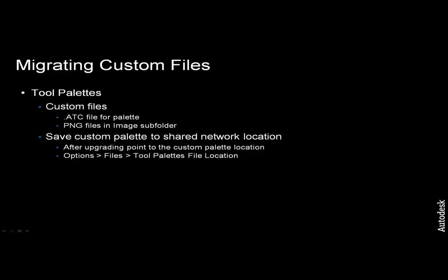It may be useful to save these custom palettes to a shared network location, and after upgrading, point to that custom palette location. You can use the Options, File, Tool Palette File locations to do this.